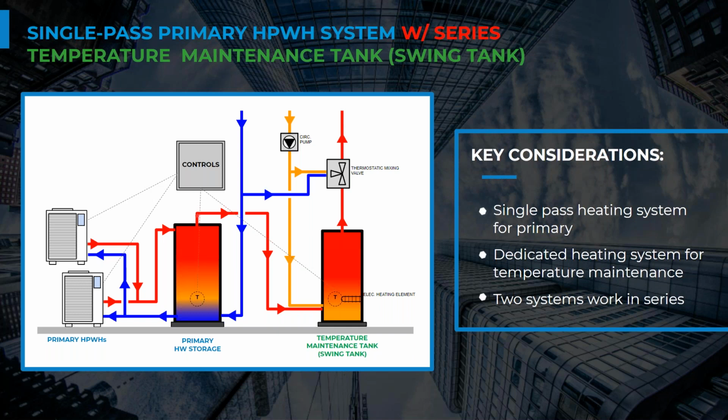That water, in the swing tank design, needs to be close to 150 degrees Fahrenheit because we want it to be as far above 120 degrees Fahrenheit so that we have overheated water and essentially extra energy that we're transferring into our swing tank. So we get a flush of 150 degree water because Suzanne took a shower, and we get our constant recirculation pump flow rate. That's probably a lower flow rate than Suzanne and a bunch of other people showering, which is typically lower.